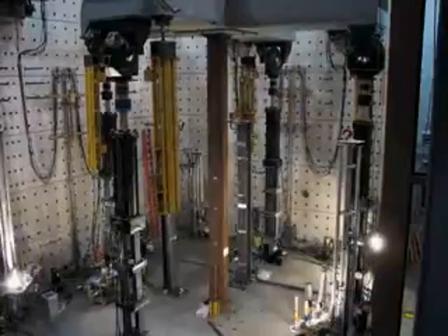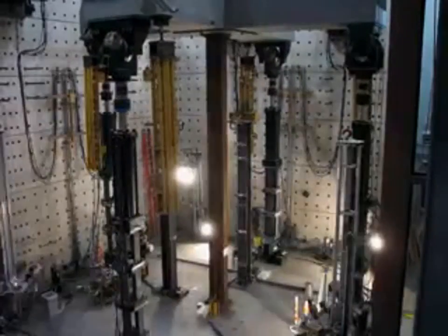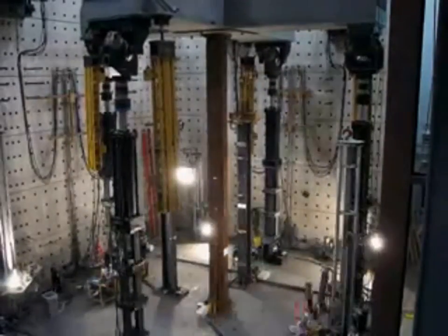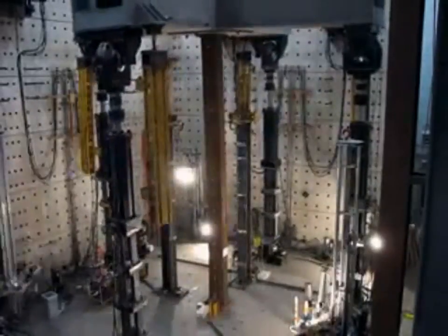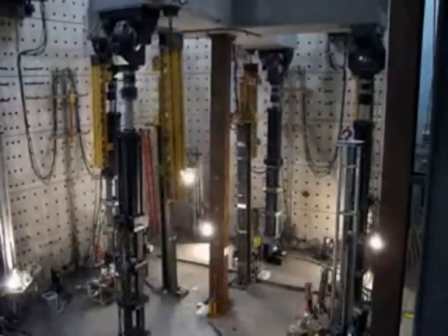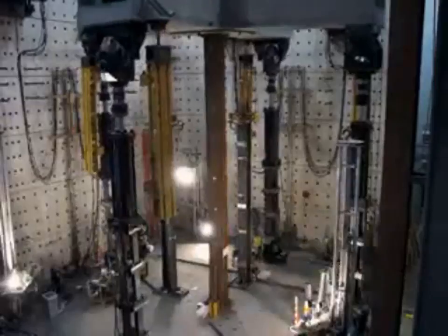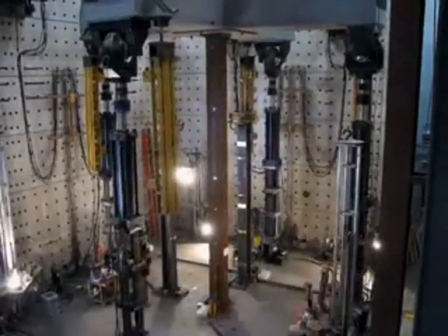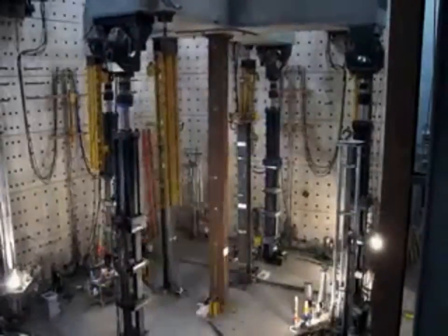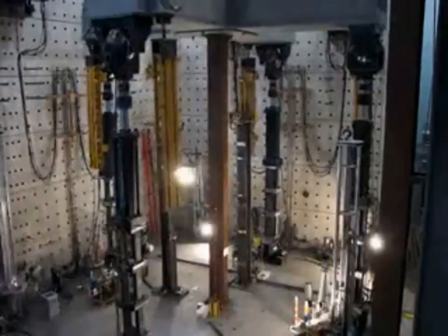And what's happening here is there is a uniaxial flexure back and forth during the first part of the video. And then they move to a figure 8 pattern of force application toward the second portion of the video. So they were getting a lot of data on biaxial flexure, uniaxial flexure, and the capacities of these columns.